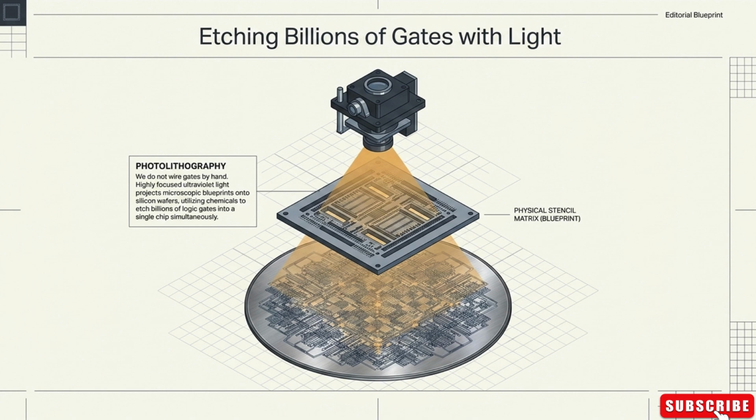No, definitely not. It requires a process called Very Large-Scale Integration, or VLSI. Engineers aren't sitting there with tiny tweezers wiring these gates together. They use photolithography. They essentially use highly focused ultraviolet light to project a microscopic blueprint onto a tiny wafer of silicon. And then they use chemicals to etch millions or even billions of these transistors and logic gates into a single chip simultaneously. That is incredible.